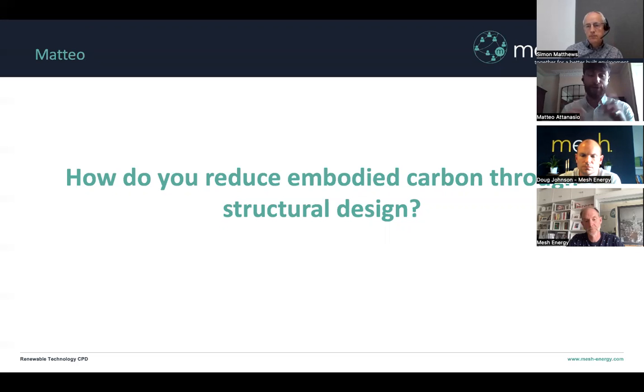And finally, just minimizing waste. We should be designing so that buildings can be taken down with ease relative to how they currently are deconstructed. We should be designing nice, simple steel frames with nice bolted connections that can be unscrewed. You can drop the beam and you can use it somewhere else. Like Simon says, we should be walking past a bit of rusted steel and see a building material. We have to completely change the way that we look at the materials that we've already produced, that are already in circulation, because we've got plenty of them. And unfortunately, 1% of them are reused. It's incredibly low. We recycle a lot of them, but 1% of them are reused.